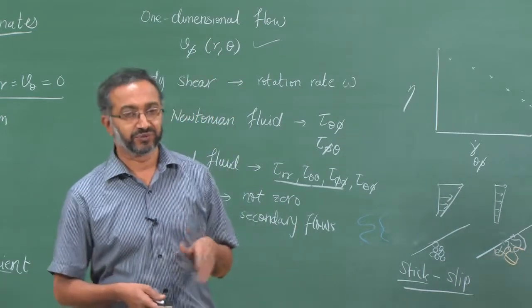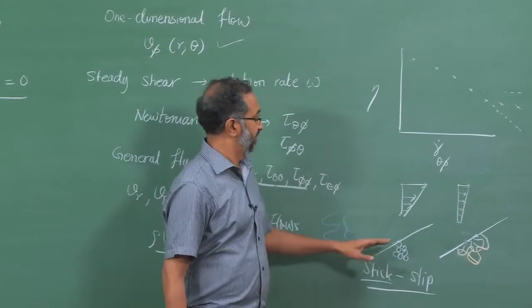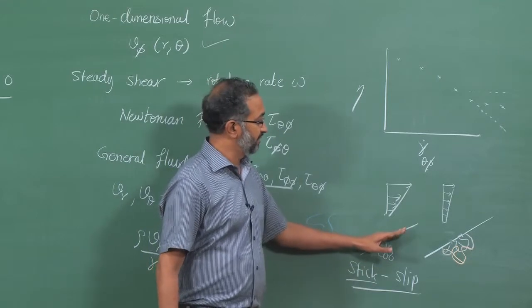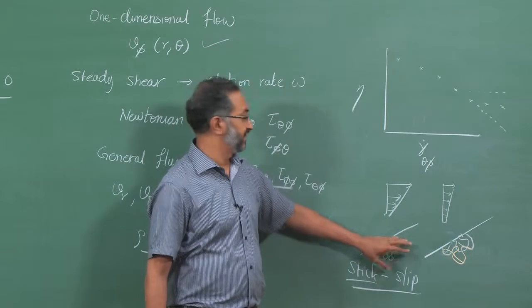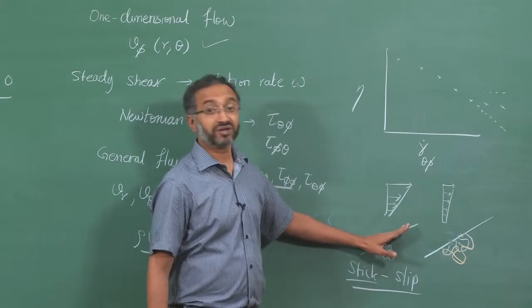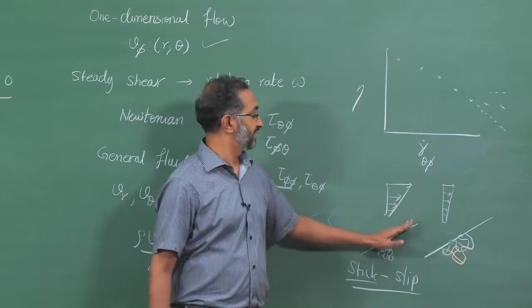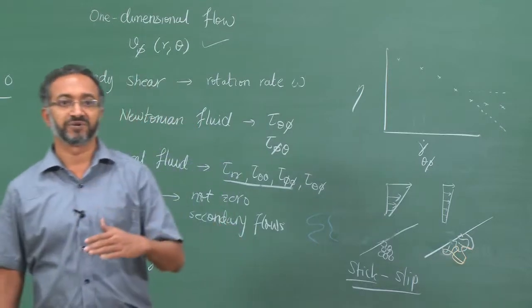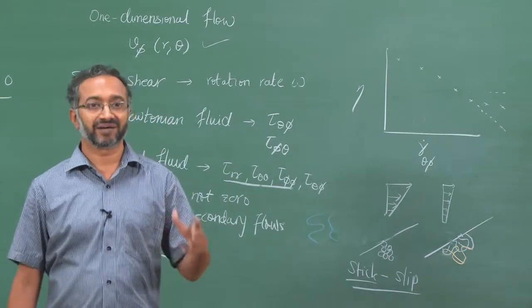So, you can modify the surface or you can change the material also. For example, if I have a suspicion that this material is very hydrophilic and the surface is not hydrophilic enough, and therefore there is a partial slip, I could use Teflon, an extremely hydrophobic material, for the geometry. That way I will ensure that more slip happens and then I will examine the result.